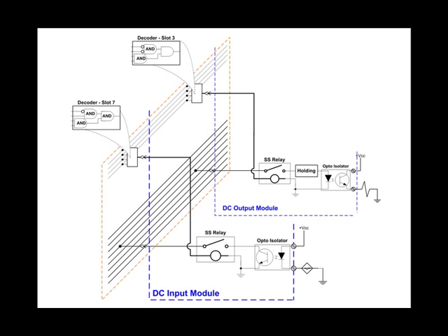If the I/O card supports 32 inputs or outputs, they are still handled 16 bits at a time. Each 16 bits is one word. So a 32-bit card has 2 words associated with it in memory. So 32 inputs or 32 outputs would be handled one word at a time. So a card that has 32 inputs takes the same amount of time as 2 cards, each with 16 inputs. If you use a 32-bit card, with 32 inputs or 32 outputs connected to the card, the processor activates the circuit card twice, once for each group of 16 bits.